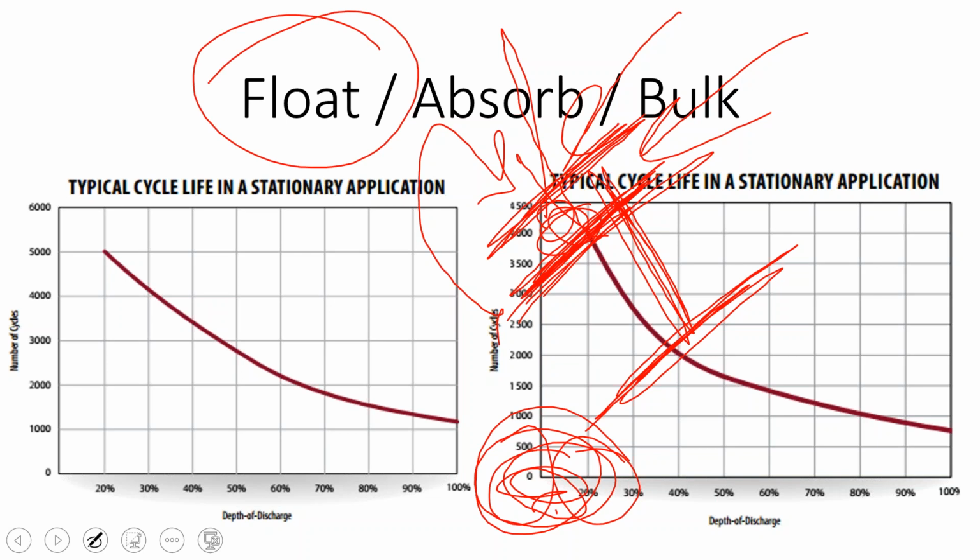Like if you live off grid, you may have enough energy to top the battery up to the top, but when you run these battery maintenance cycles to cram even more energy into it to get it up to the top of the 60 volts, that's called your float phase. And you're really only doing that maybe every 2 weeks during heavy use, and maybe once a month during the spring and fall when you're not really running your battery all that much.